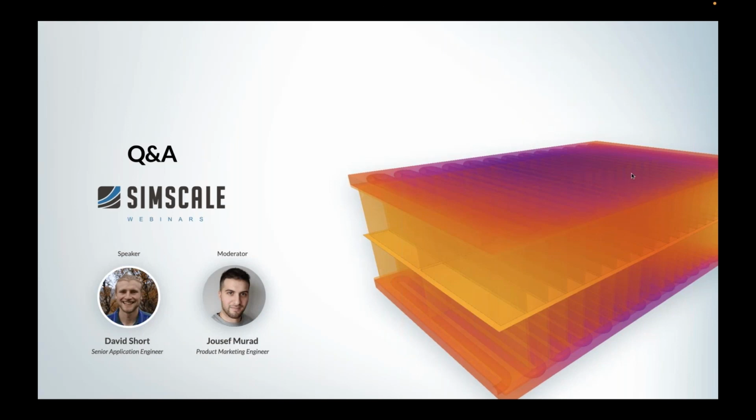Cool, thanks, David. A very interesting question, because you used the thermo-mechanical module here of SimScale. Another question we have coming in is about forced and natural convection. Can we model things such as fans, heat sinks, things like that? Absolutely. My CFD colleagues will be very happy that you've asked that question, because that brings you into the world of CFD. So bringing together both the internal thermal conductivity in your solid bodies, but also the convective behavior in the air. To simulate the active cooling or the passive cooling explicitly is going to require a coupled CFD analysis. And that is absolutely something that we offer in our conjugate heat transfer simulations.